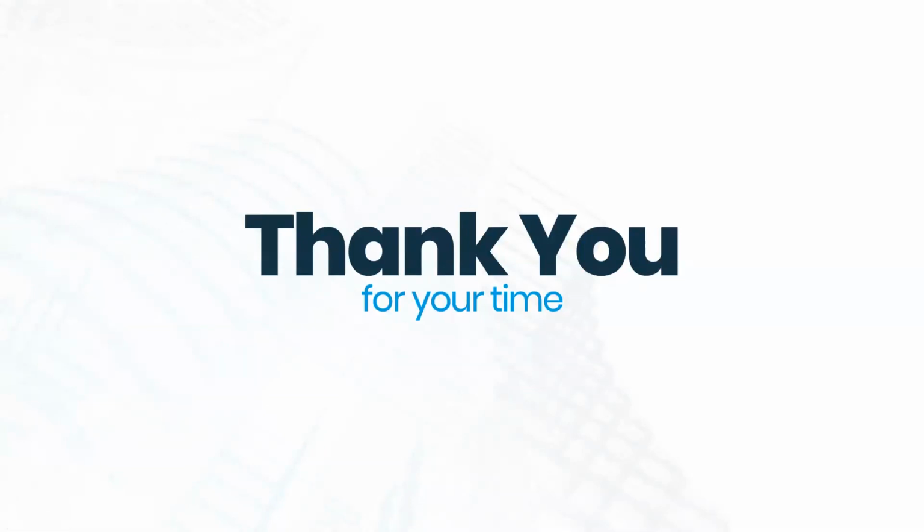Keynotes have boxes around them on the drawing. Can those boxes be put on the legend too? When it comes to the keynote legend, it is just like a schedule. So all the functionality you have in graphics of a schedule also applies to your keynote legend.